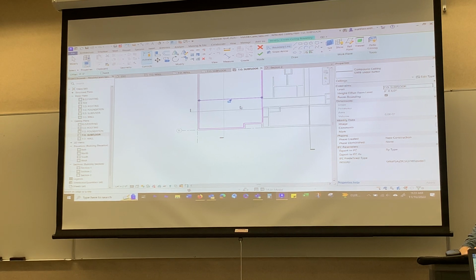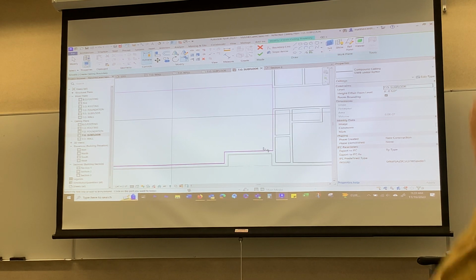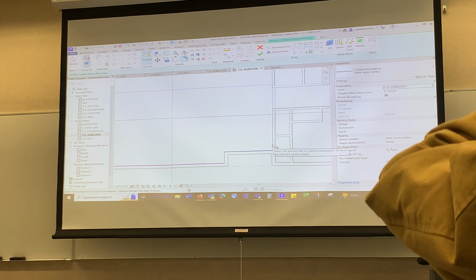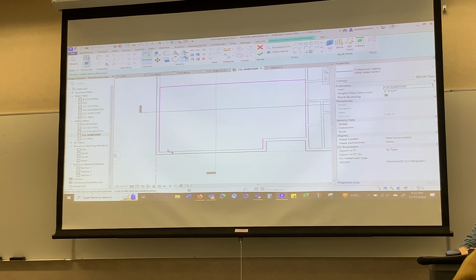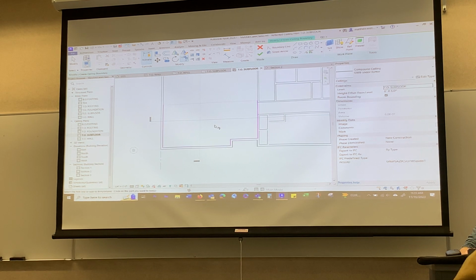And then obviously you have to neaten this just like anything else. So you're gonna use your trim extend the corner tool and trim these lines. Like so. I just trim them off because I'm used to this thing messing with me. It looks like it's closed, but I'm gonna trim every corner anyway because I don't wanna have to do it a second time. Okay? So that should have that piece of ceiling in there.